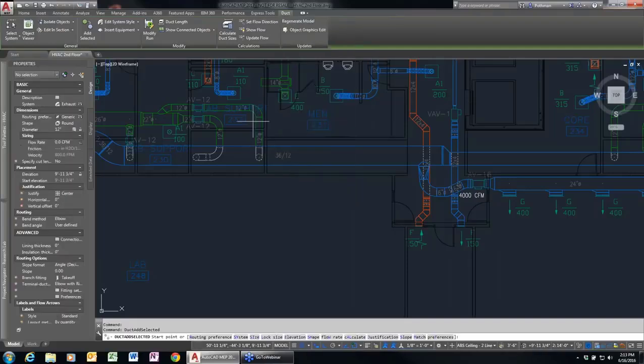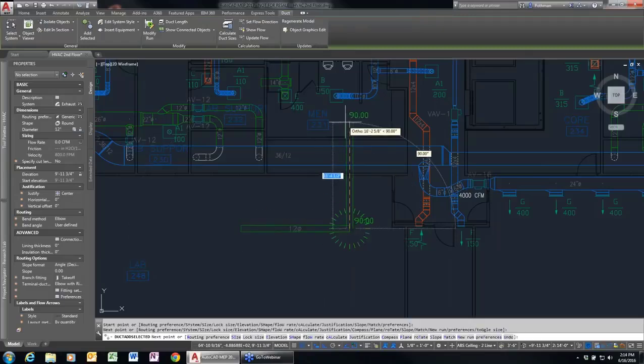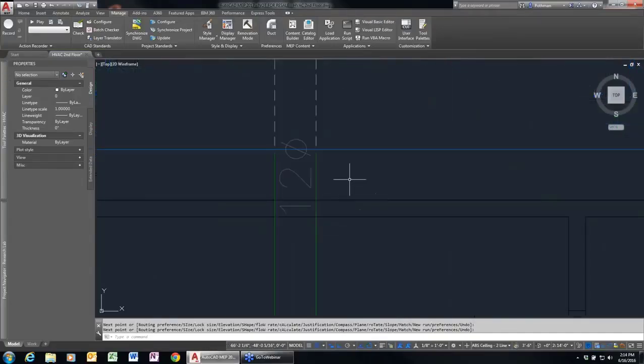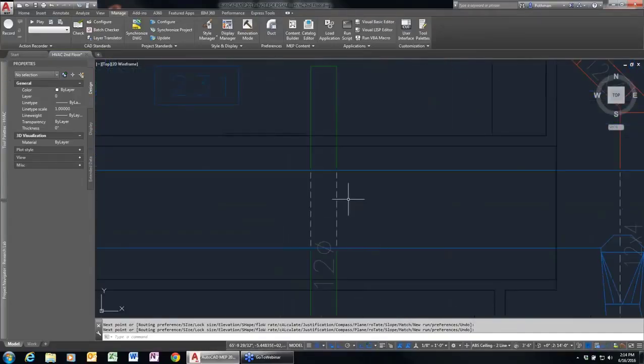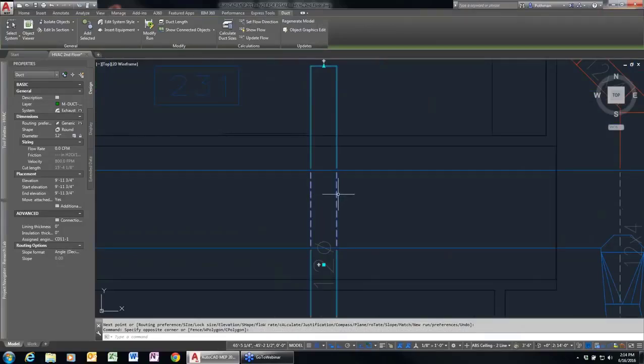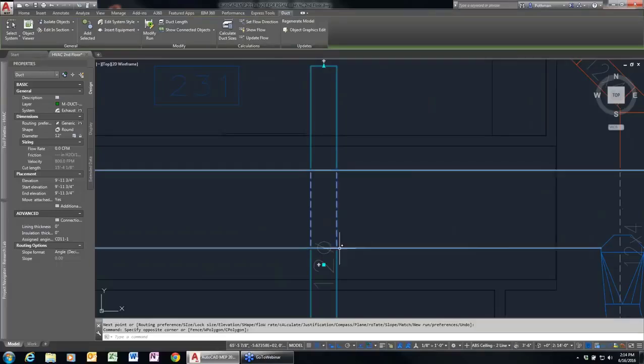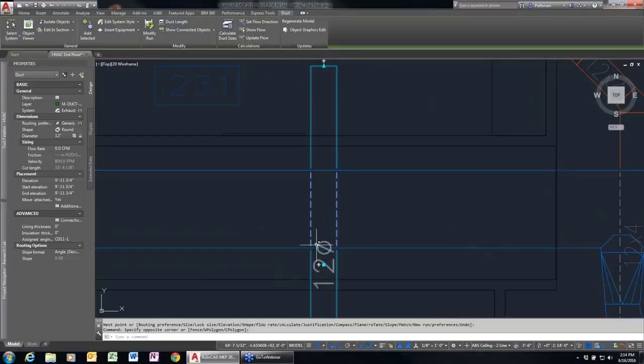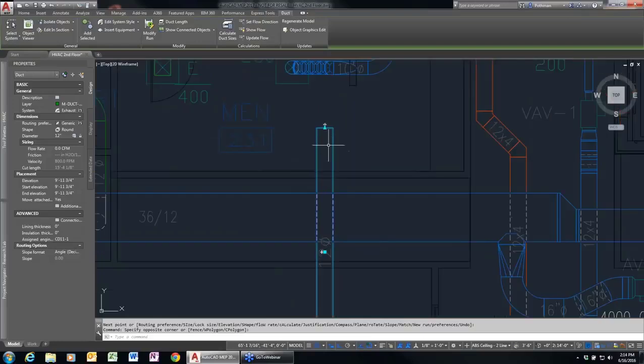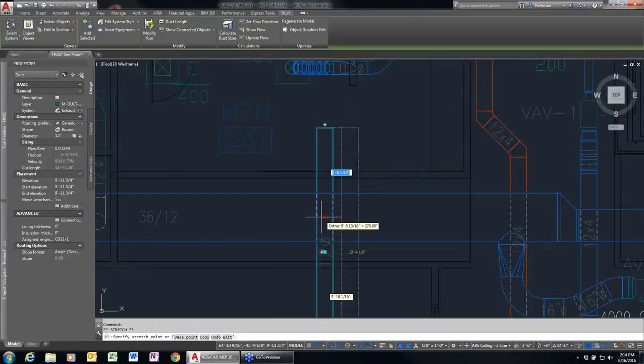So when I do an Add Selected, it automatically sets me to drawing an exhaust duct using my slip joint fitting, round, 12 inches. And if I were to just come over and draw this across another duct, you're going to see, just scroll down here a little bit, that the duct that's underneath the larger duct is automatically displaying with hidden lines. I didn't have to stop and break them and create a different layer or anything like that. It will just automatically change to show what you need to.